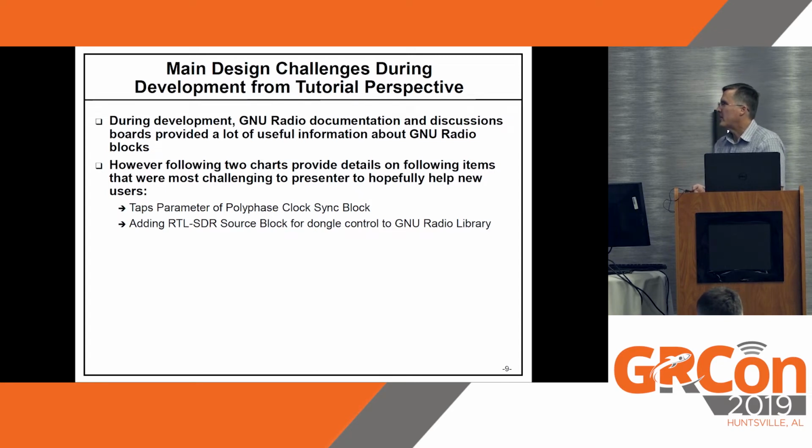So since this is really a tutorial type presentation, I wanted to, since I was a new user, list a couple things here that gave me trouble when I was developing the receiver, the TAPS parameter in the polyphase clock sync block, and just getting that RTL-SDR source block into the GNU block library.